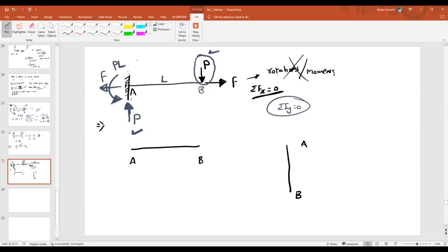From this we can observe that because of axial forces, moments will not generate on the element. It doesn't matter what the orientation of the element is. If axial forces are acting on the element, they will not cause any moment. If vertical forces or shear forces are acting on the element, rotations may develop. To avoid those rotations, resisting moments should develop.